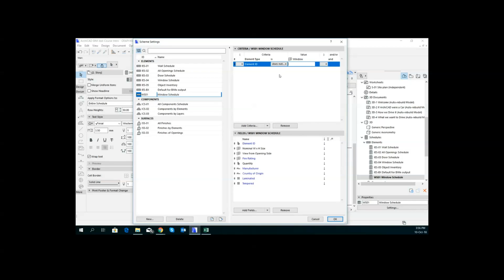So Excel, we're just using that as a method to quickly edit, add, redact information, whatever the situation would be. That's not as an export tool, so we shouldn't find that schedules are made or finalized in Excel. Everything's still controlled in ArchiCAD. It's just a way of manipulating lots of data quickly, because you know how you've got repeating data. In Excel it automatically suggests the entry if you type the first letter. So that allows you to go through quickly, put all that data in, and then bang it back into ArchiCAD.